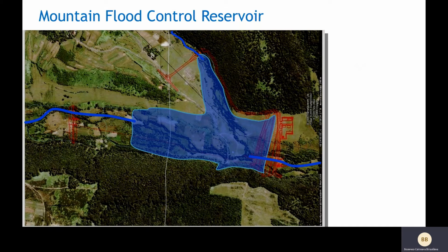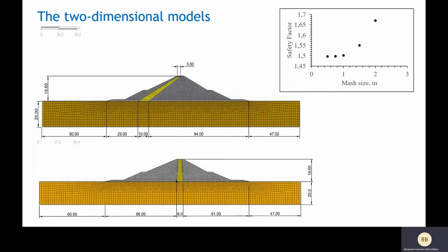The purpose of our work is to simulate the possibility of a dangerous landslide process of the upstream dam slope during the reservoir operation, and to determine the optimal design of the impermeable structure of the rockfill dam. Two-dimensional models of the dam with the core and the dam with the screen were used to simulate the reservoir operation.